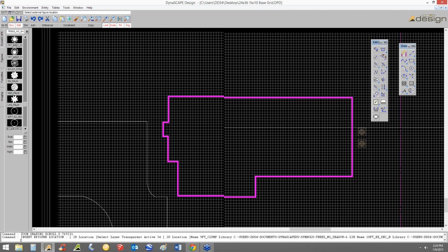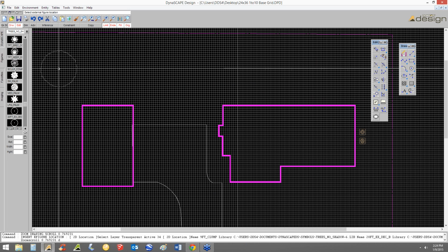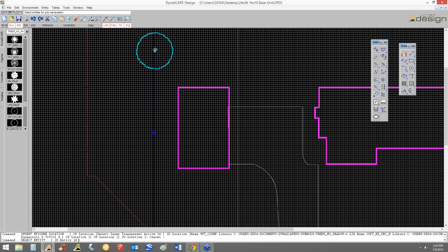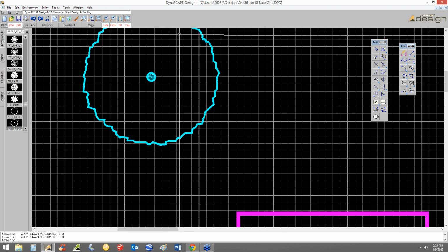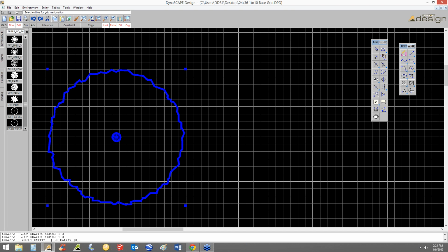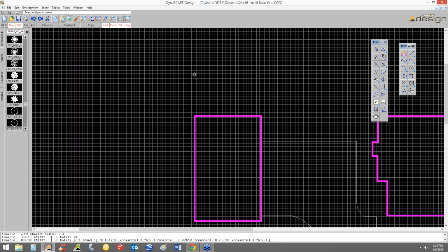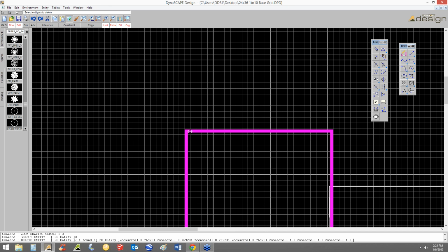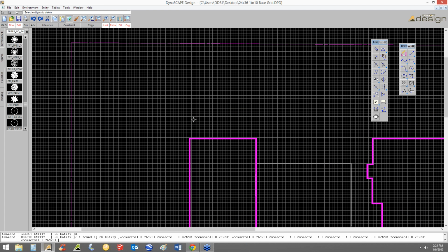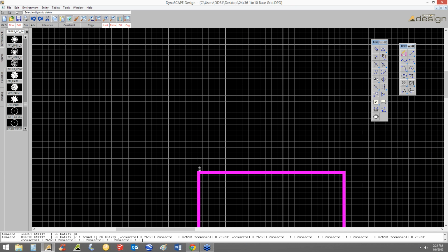Let's say they have these trees out here that we want to locate. Let's get rid of that because I'm going too quickly. And we want to locate those trees. All you need to do is measure off of maybe the back corner. So let's say it's 15 feet back and 30 feet over. You could go 1, 2, 3, 4, 5, 6, 7. Let's just pretend this is 15.